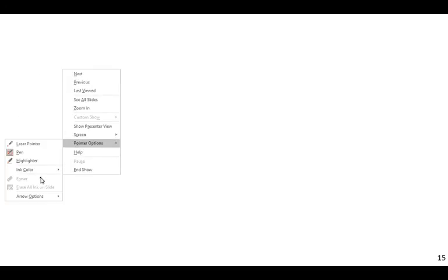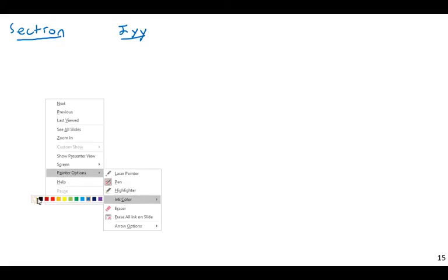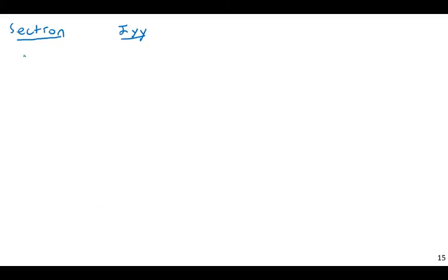Looking through the table, the way I do this is I look at the series of shapes, and within each family, like the 8, the 10, the 12, etc., I find the lightest one that will have the required IYY. I got these sections from the steel table.